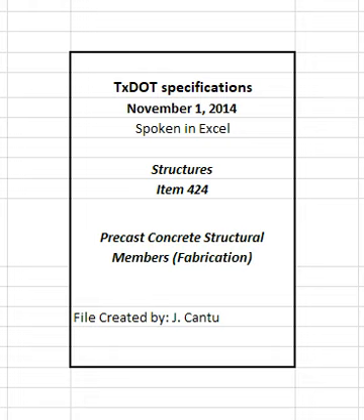Provide curing enclosure air temperature probes to monitor the temperature at the concrete surface as specified in Table 2. Provide enough moisture inside the curing enclosure to keep exposed concrete surfaces continuously wet for the specified curing period. Provide other acceptable curing methods for the remaining curing period if accelerated curing is terminated before the specified curing period has elapsed.